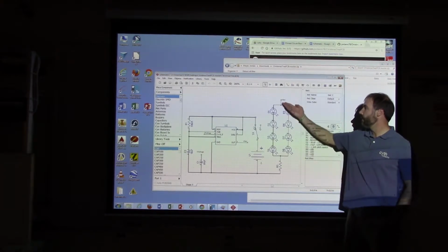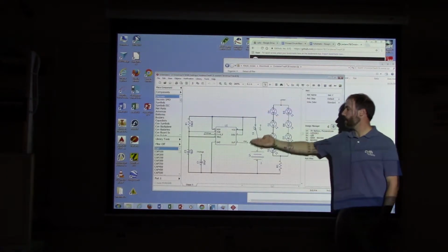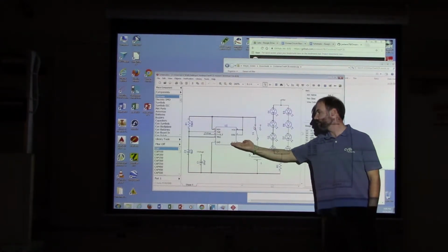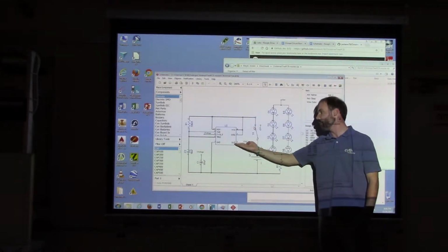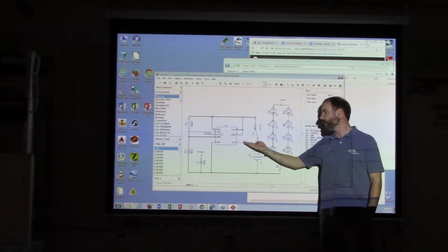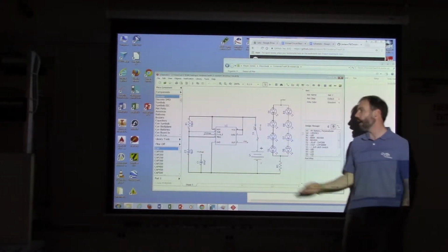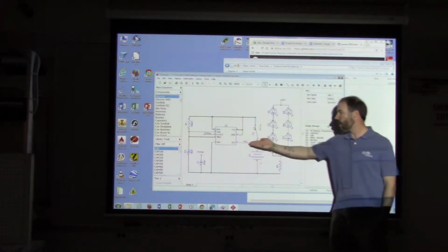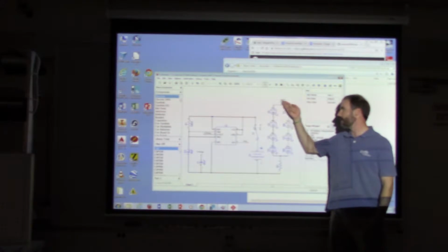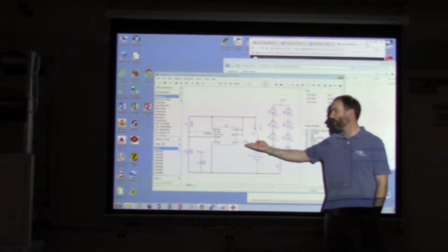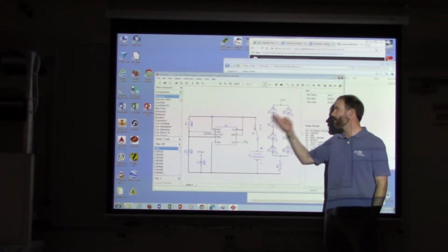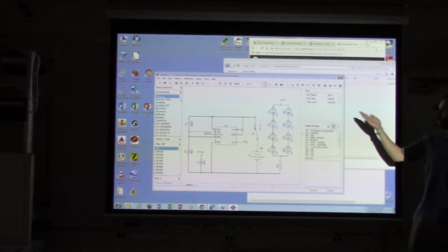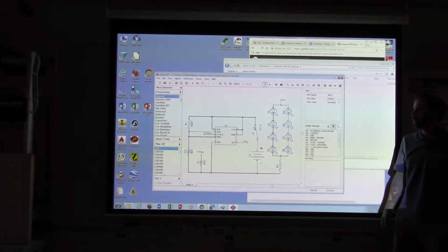In those cases, you can make a connection by using a name, right? In this case, this terminal of the chip was called the output voltage, so we labeled this wire V out. And we also labeled this wire up here V out. And by calling them the same thing, exactly the same name with the same capitalization and everything else, the computer recognizes that we want to connect those two points. So we can make that connection without actually drawing the wire on the sheet.